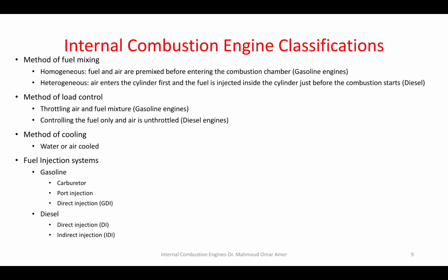So when the injector injects the diesel fuel, does it have enough time to mix well with the air? No. The mixing isn't well. You will find areas inside the cylinder with very, very rich mixture, and areas with very, very lean mixture, and areas where the mixture is stoichiometric. It varies inside the cylinder. This is called the heterogeneous mixture, not homogeneous. The mixture isn't good between the air and fuel. And we will explain the combustion behavior of diesel using this mixture. Okay?